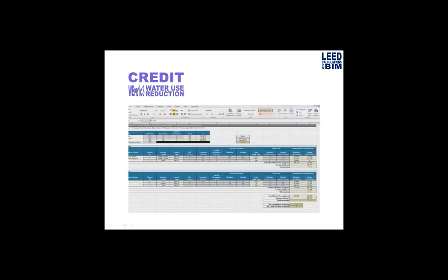That's a really good question. You are going to find, and I will talk about this a little bit, there are going to be some cases, because of the limitations between scheduling information across linked models with Revit, where you are going to have to copy over some elements or copy monitor some of the elements, and like this person said, you do lose shape edited floors. So in that case, you would probably want to copy those elements, and that's one of the downsides of working across linked models. If Autodesk can work out that function and make it so that you can schedule and be able to access and then do some calculated values across elements that are in different linked models, that would be great. But right now, that's one of the limitations.